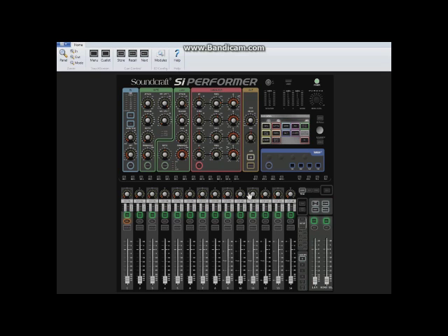Now, we're going to pick one microphone to set here. Let's say we pick microphone 1. Over here you see this button is pushed as left and right. That will represent a stereo-only mix. So we're going to push mono also. That's going to allow us to mix left, center, and right, with the masters for left and right being here, and the master for the center being here.